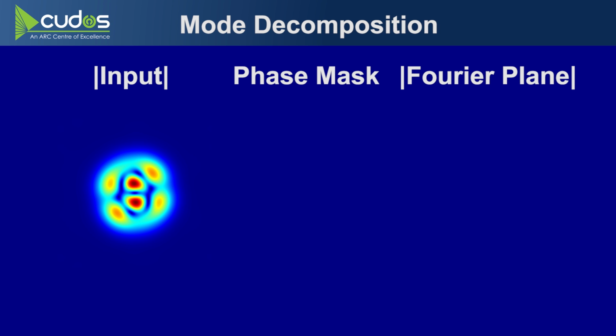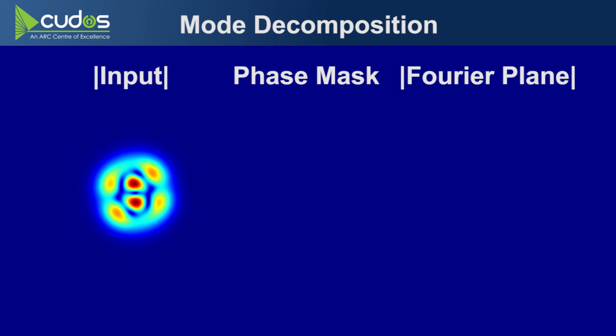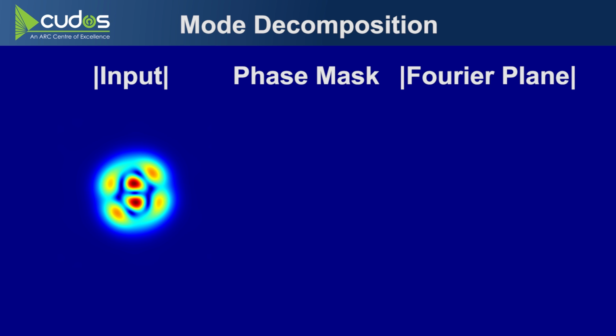For example, if we're ignoring polarization for a second, here's the mode arriving at the receiver as some random superposition of LP12 and LP31 modes. In the middle will be the phase masks displayed on the SLM in the image plane, and on the right is the Fourier plane representing the plane of the output single mode fibers, which are attached to a power meter.